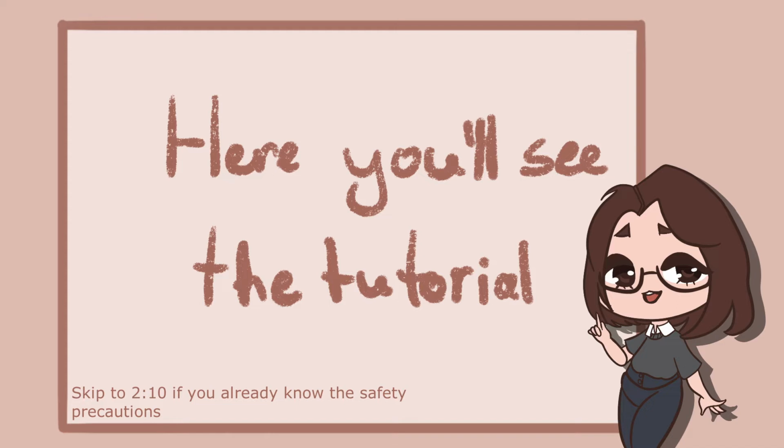If extraneous noise is detected, stop working and de-energize the equipment. Do not store flammable substances near the equipment. It is not allowed to work with reflected metals as well as materials that are sensitive to high temperature and emit toxic substances. Ensure a CO2 fire extinguisher. Do not use powder fire extinguishers as they can damage the laser parts.